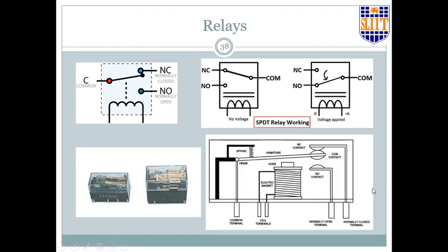You may have only normally open contacts or normally closed contacts, or both, or multiple numbers: some number of normally open, some number of normally closed. Sometimes there will be single pole, single throw switches inside. Sometimes there may be single pole, double throw switches. It depends completely on whether you put a probe or not. The mechanism would switch, but if you don't have a contact on the other side, you don't have any electrical conduction going, right?